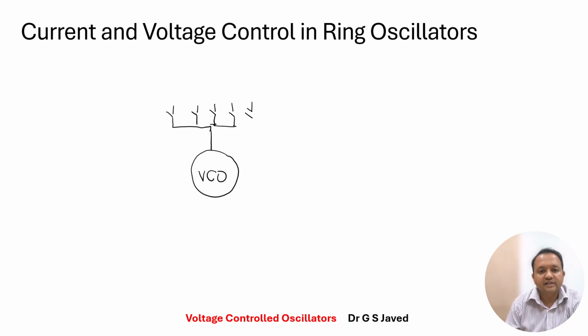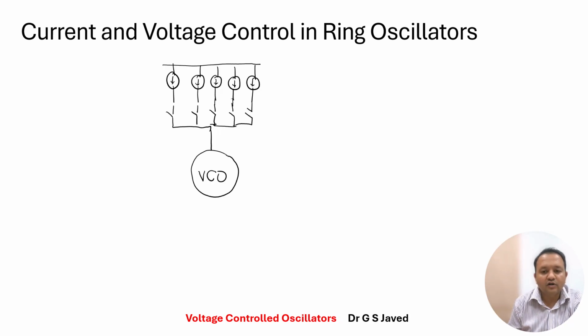In this particular case, as an example, I am going to use 5 current sources. Each of the current sources is going to be binary weighted or thermometric weighted. The center line will have the always-on current source, the smallest value, which we will call I. Then the next nearest one will be another I, such that we can have 2I, and the adjacent one will be 2I.